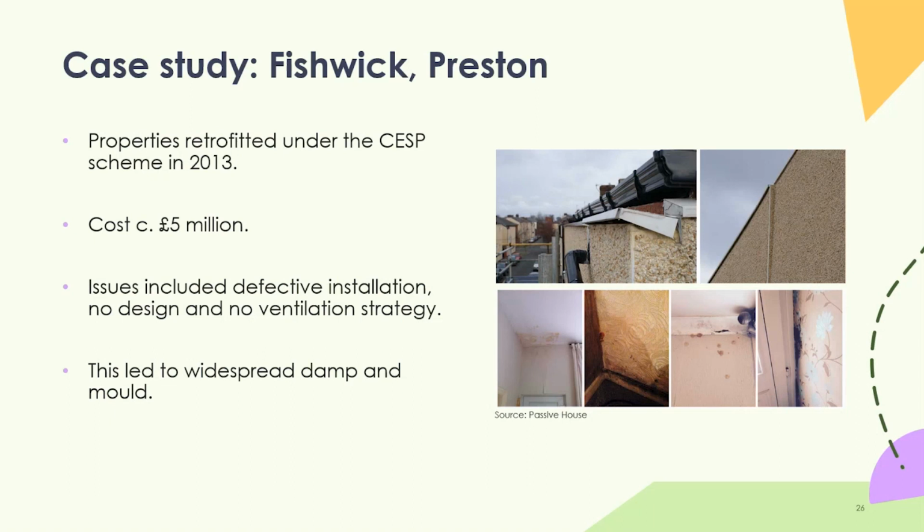That led to very high levels of humidity throughout the house, and then one thing led to another. You've got mold all over the place, damage to the plasterwork and the brickwork. Everyone had to be moved out, and there were horrendous costs for repairing all of this: removing all the insulation, repairing it internally and externally, and the costs of rehousing people. You can imagine it just goes on and on.